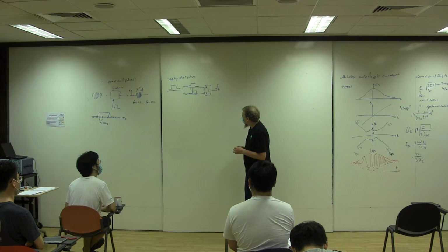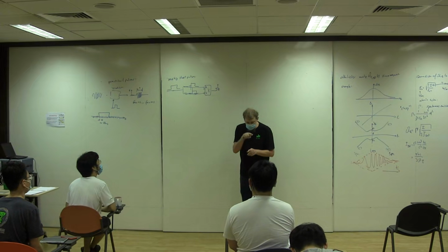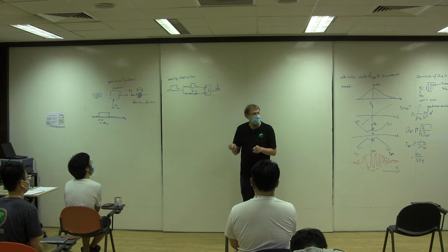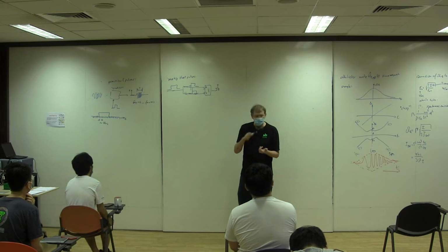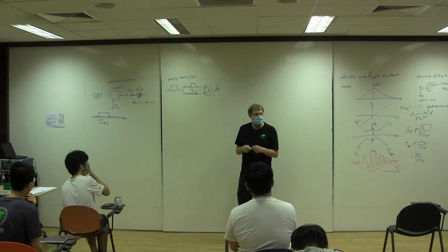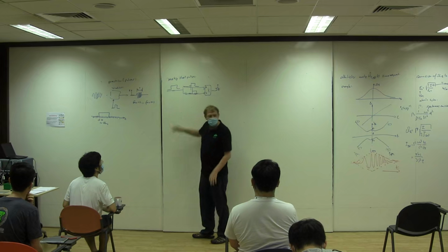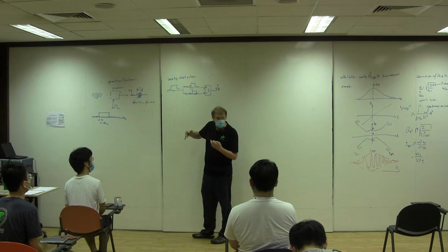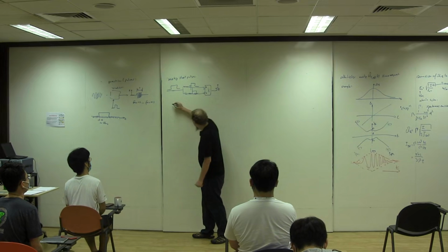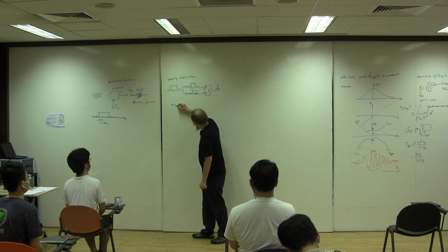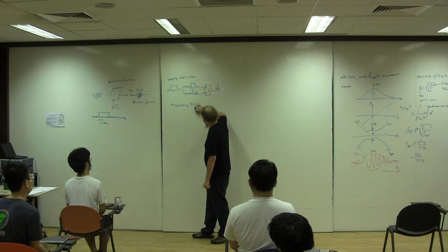The other trick you should probably be aware of is, now this gives you just the envelope of an electrical signal, and how can you use it to modulate, say, a radio frequency signal that you would need for your acousto-optic modulator. Okay, so whenever you have a pulse, you often want to modulate not directly a phase modulator, but a radio frequency. That's a typical scenario you have, modulating RF frequencies or signals.